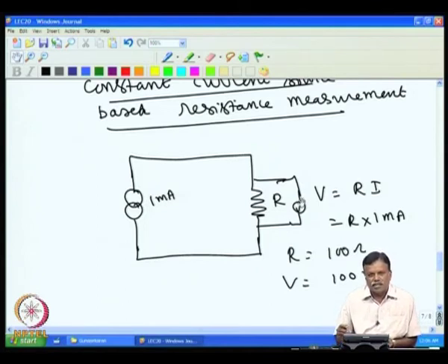So, all these things make this system less accurate compared to our bridge method which we have discussed, where this problem is not there: no calibration error, and no voltage drift error. Even if the excitation voltage changes, it produces no effect at the null point. I hope now you understand why the bridge technique is still surviving in spite of such a modern development. The bridge is still surviving because it is the most accurate measurement that one can make.